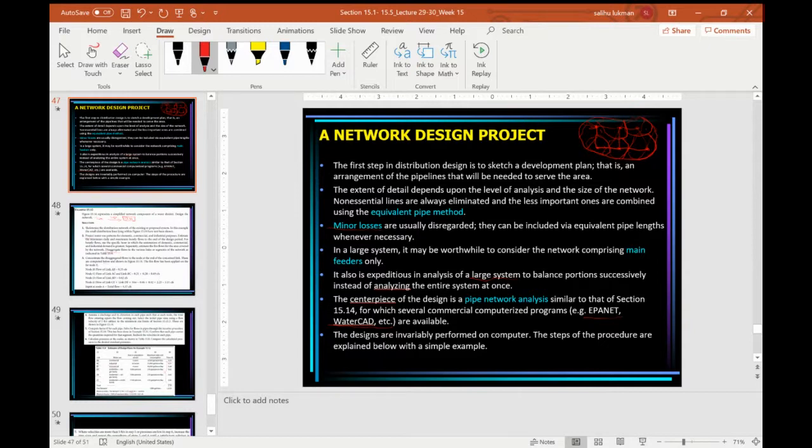That is using the topographic map, finding the pipe sizes, carrying out the analysis, checking the velocities and pressure heads, and adjusting where necessary, and then coming up with the design flows of each pipe, and sizing the other components of the water distribution network, like pumps, tanks, valves, and all the other appurtenances.